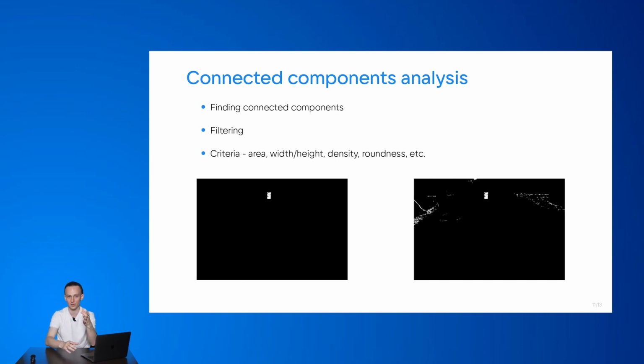If we want to detect only the ball, which let's say could be white, but not the goal posts, we can filter the objects by the ratio between the height and the width. If it's close to 1, it could be a ball, that's fine. And if it's, let's say, 5, it's clearly not a ball. The ball is like a circle in the image. It's not elongated that much.